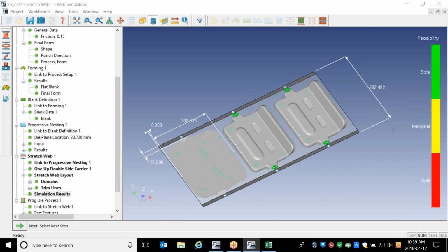Mike, we're running the 2017.2. So at the very beginning you ran through opening up a new project and zipping through defining material and punch direction, and it seemed like it went fairly easily, and your punch direction and your plane was fairly simple. What we're running, it almost seems as though you have to manipulate your XYZ axis when you're defining your punch direction in order to get a nice level where you want that die plane to be.